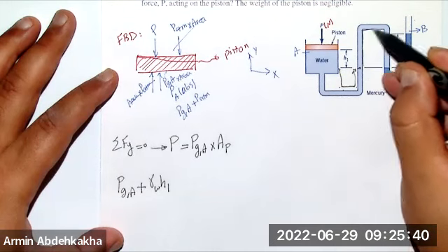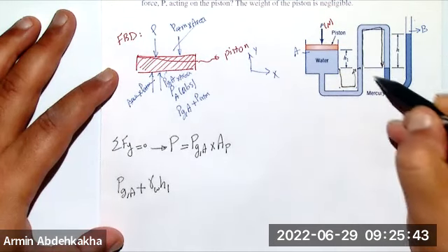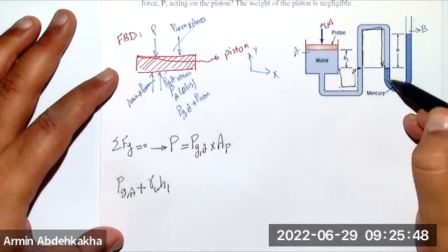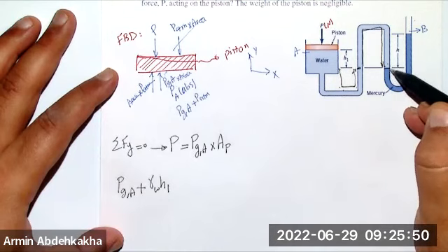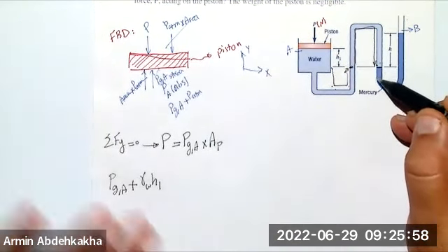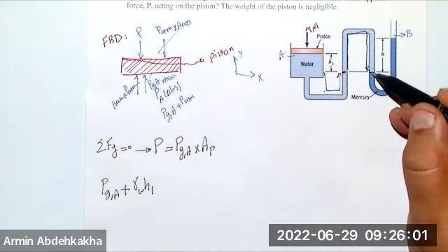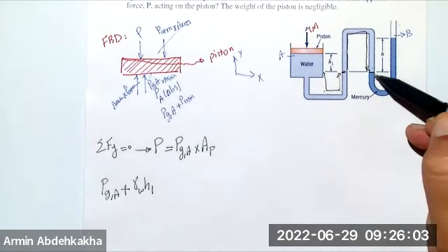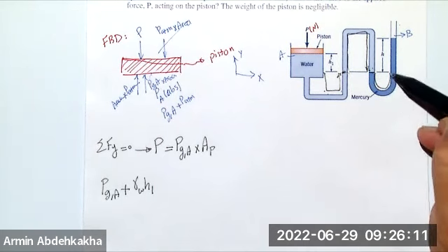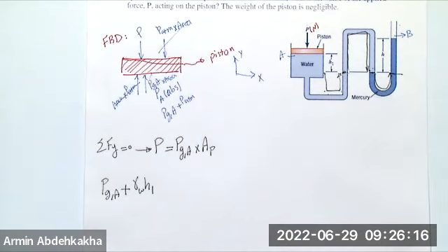If you have two fluids, at the intersection of these two fluids you have the same pressure, because this is at rest and in a steady equilibrium state. Then the pressure here is the same as the pressure here. And again, you come down and go back here, and you can jump here because the pressure is the same.